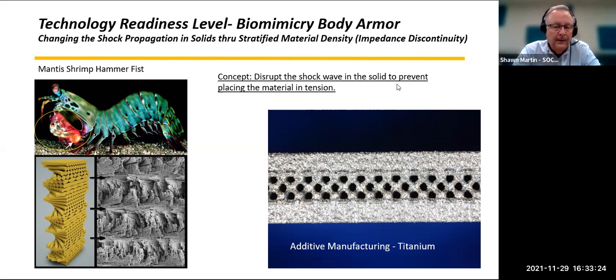And so we did that by changing the density of the metal, and you can do that with additive manufacturing by the process of either the dwell time or the electron beam or the laser, and how much powder you put down and what shape you put the powder. And as you can see, we have a hollow kind of honeycomb core, and it worked.